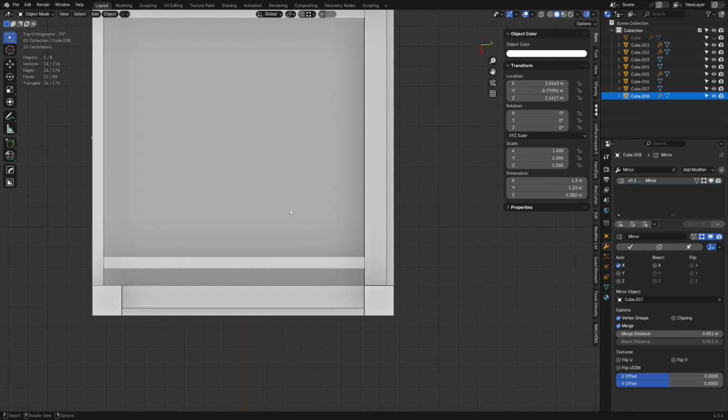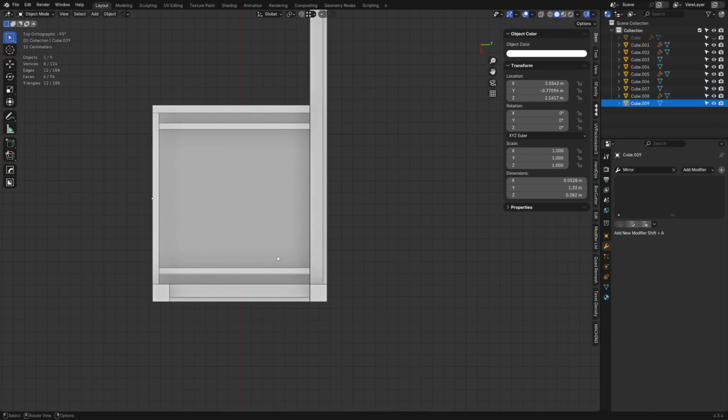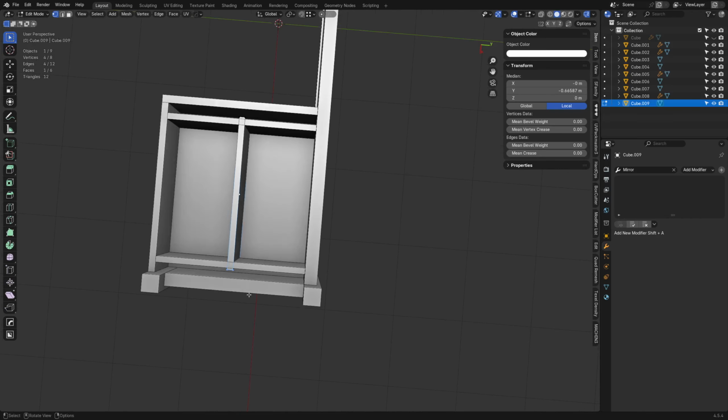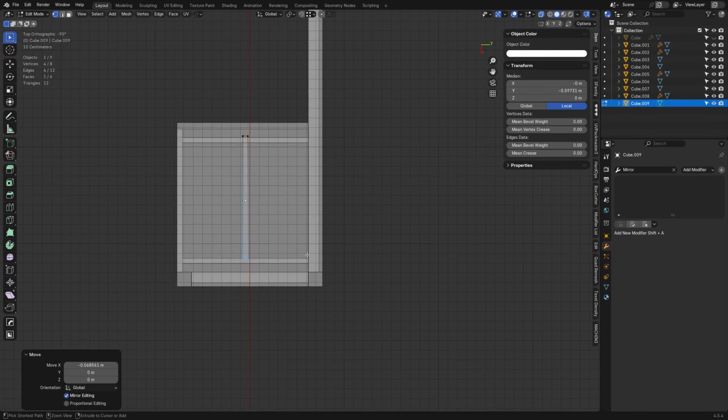We're going to want one in the back as well. So we can duplicate it, maybe remove the mirror, set origin to geometry, rotate it. There's all kinds of different ways of doing this, but you can also take this here. You see it has a location on the x-axis. You can copy it, paste it, boom, right? Go into edit mode, Alt Z it, GX hold control, snap to that interior, GX hold control, snap to that.